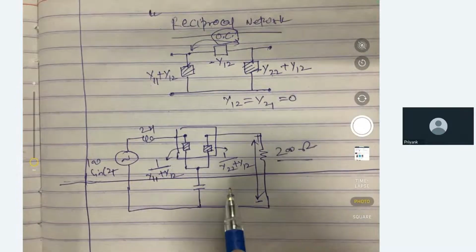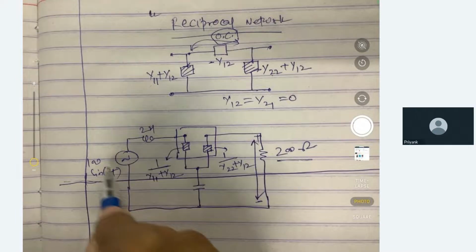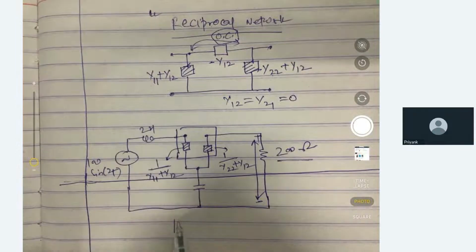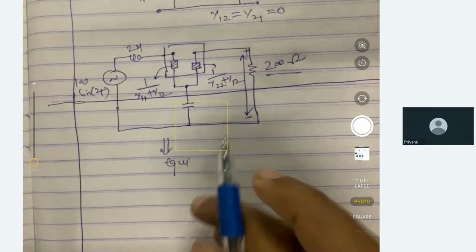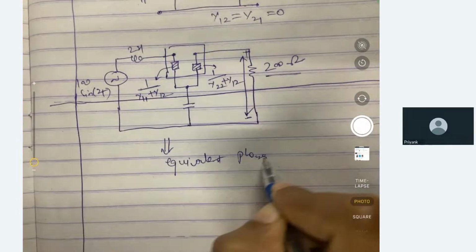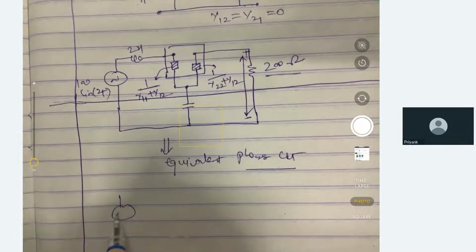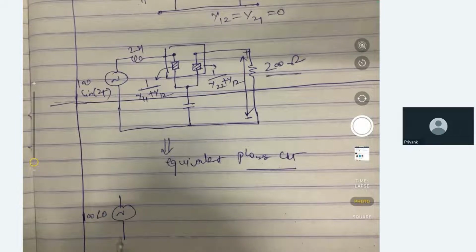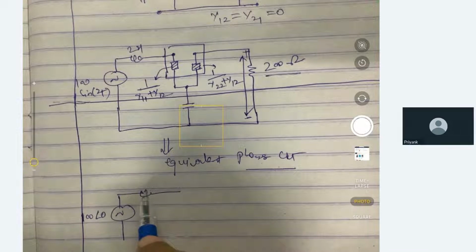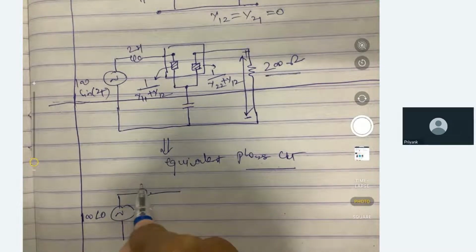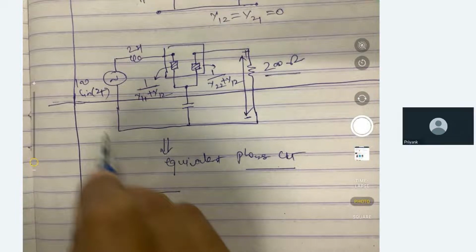Now this problem is quite easy. You can apply the phasor method, so let us write the equivalent phasor circuit. Here we can take 100 at the angle 0. The inductance in Henry is given, so the equivalent impedance will be j omega L. Omega here is 2, so 2 times 2 is 4, that is 4 at the angle of 90 degrees.